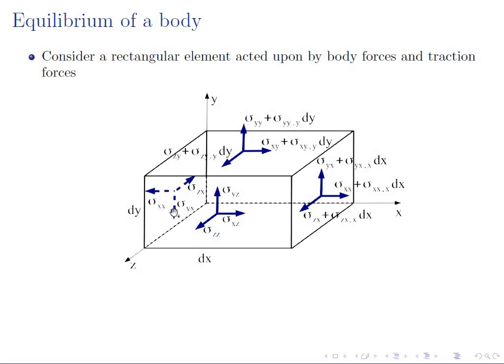let's say sigma xx, sigma yx, sigma zx on the x face, and on the other x face at a distance dx, the stresses are sigma xx plus some change in the stresses, similarly sigma zx plus some change in those stresses, and similarly sigma yx plus some change in sigma yx. Similarly, we have stresses which are also acting on the y face and the z face as well.